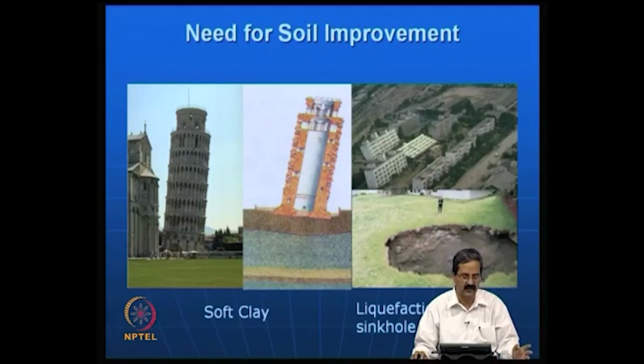So even that acceptable tilt is an engineering design. A lot of work has been done in soil mechanics and foundations. This particular case is a liquefaction phenomenon, in which the effective stress becomes zero when an earthquake occurs in the foundation soil. The foundations just get sunk in, and you have tilting or total collapse of the buildings. Then this is another type of problem called sinkhole formation.